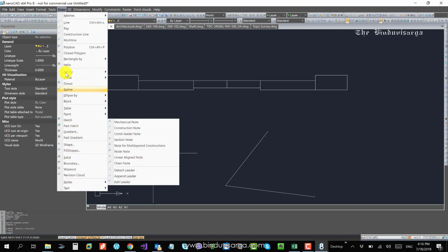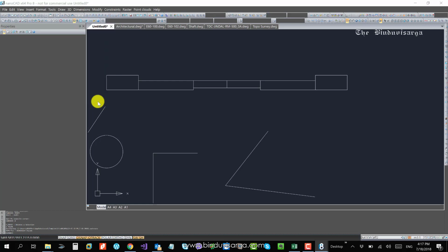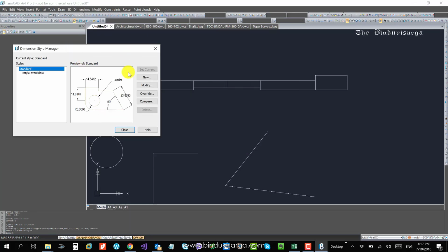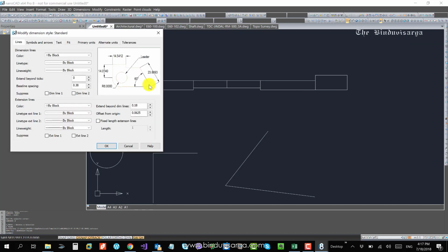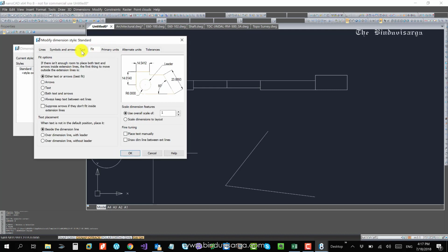So okay, moving further to the dimensions. So now if we have a part or assembly, now we need to dimension all of the objects. We can use each of the objects to dimension using all of these functions. These are all very similar. If I go to dimensions, so the dimension dialog box is also very similar to other CAD systems. So you may have used this kind of environment before. So just if I double click, I just click on the modify, and now I have a window where I can update the scale and text and everything.